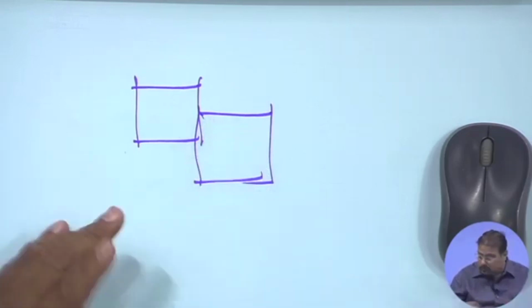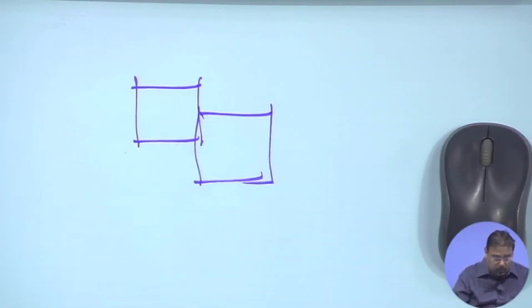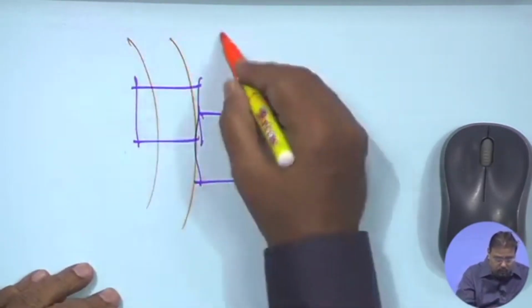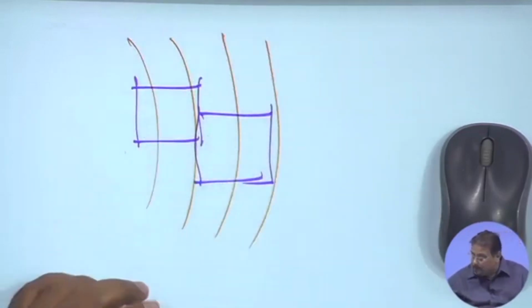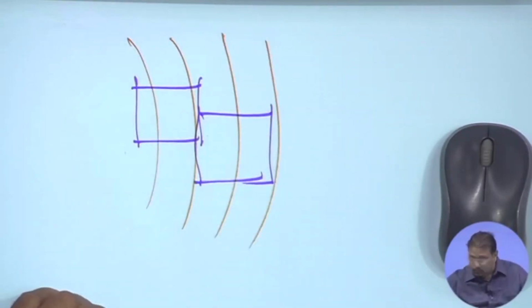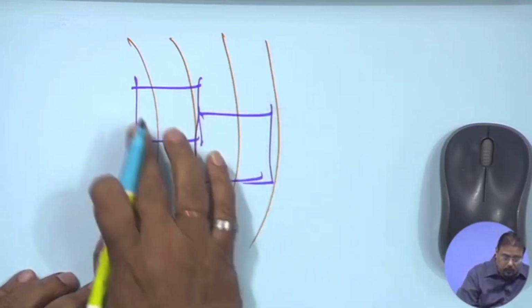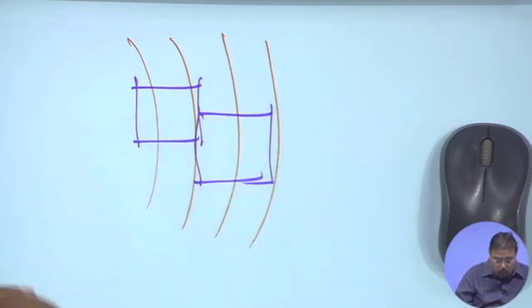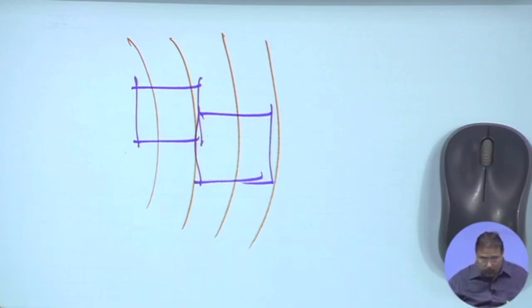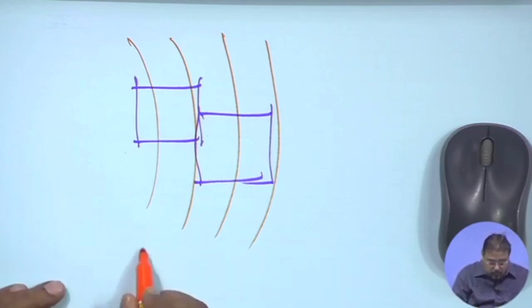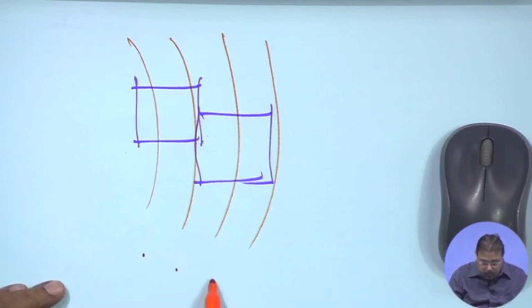Okay, in this, suppose you find that your contour line is going like this. Now you are deciding the spot level. In this particular contour line, if I try to draw the profile, this elevation, this is the next elevation, next elevation, next elevation.